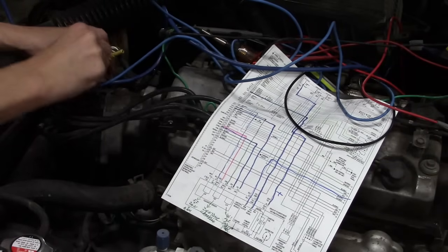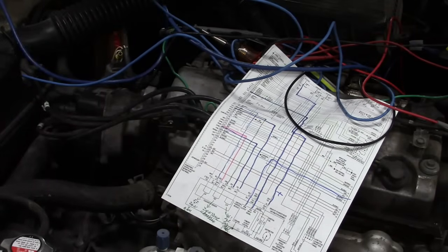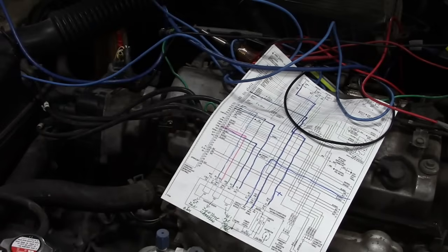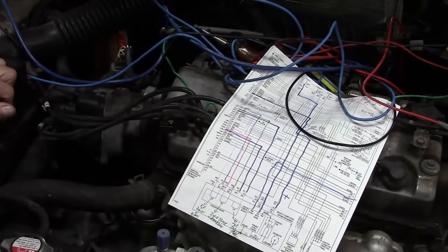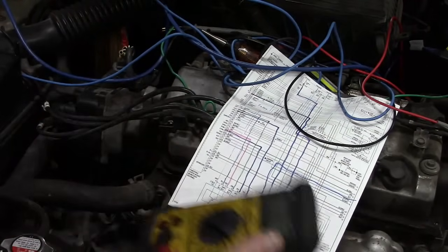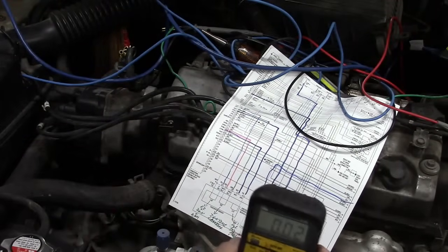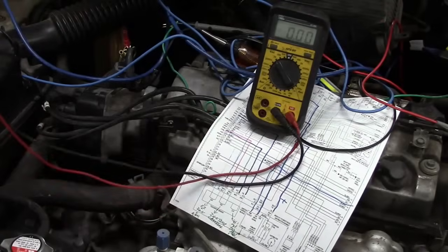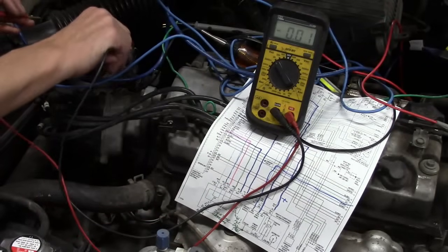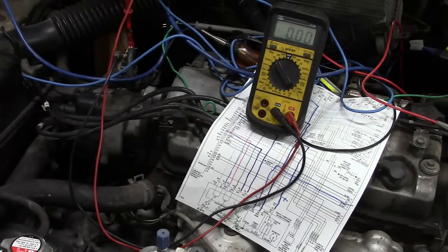And again, we know it's going to work, but I am expecting that this is going to give us a kind of sine wave pattern, not a square wave. Let's first, because we already have the DVOM hooked up, take our DVOM. I'm going to set it to a 20 volt AC scale. And this is just going to prove our concept that we know our basic electrical and we can anticipate things based on that and verify that they go according to plan. All right, let's see what we get here.